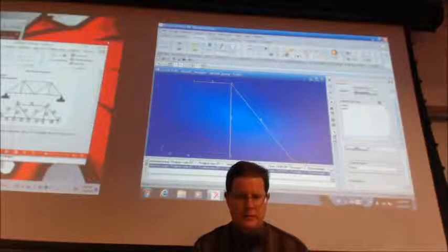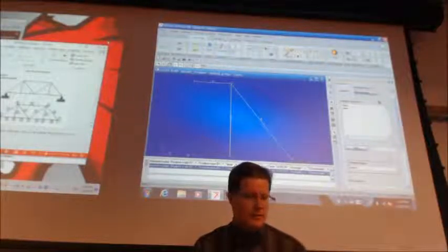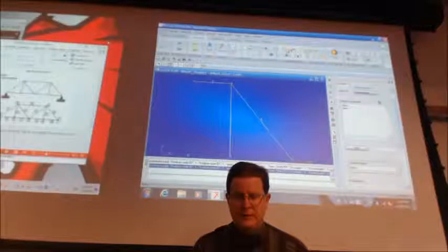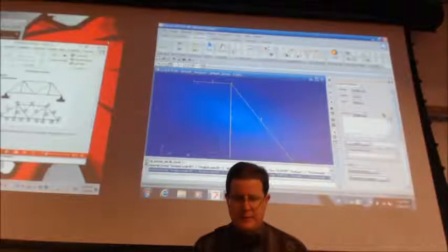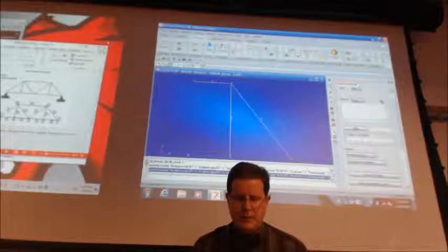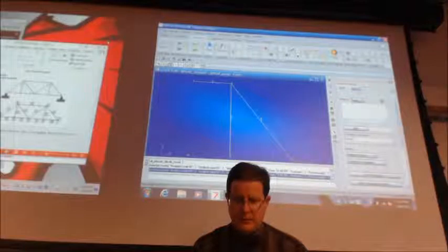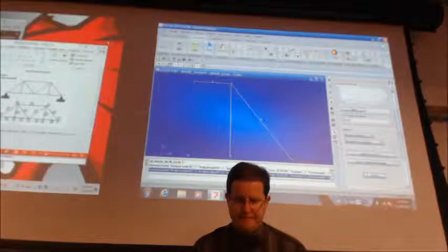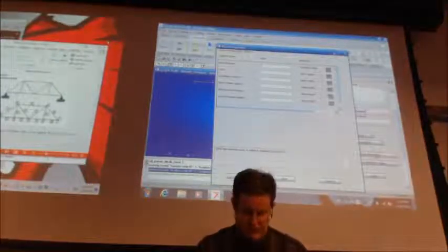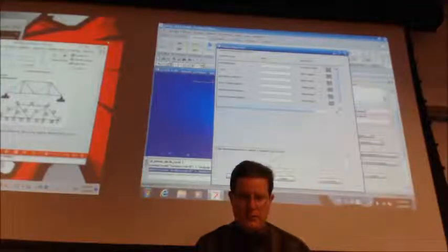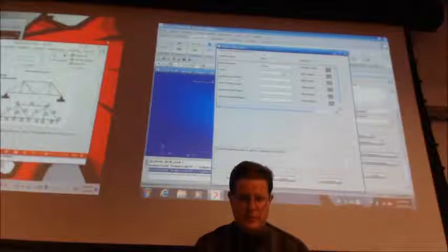And my icons, for whatever reason, are freaking out. So we want to make these 1D rods. So we'll click on that. Property set name, I'm just going to call them truss, such as it is, right? And our input properties. So we have the two materials. Let's see, so we'll just do aluminum first.